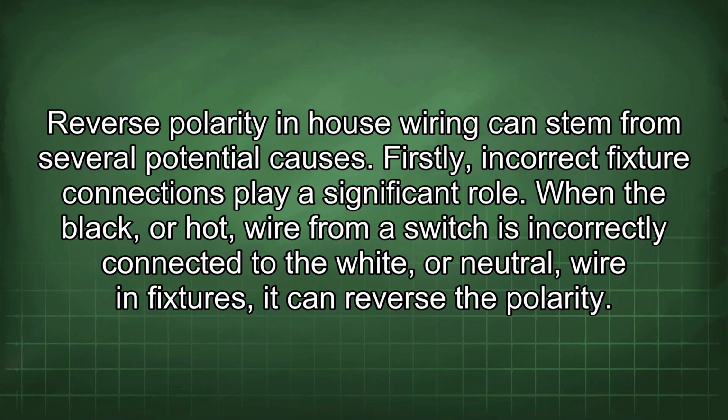Reverse polarity in house wiring can stem from several potential causes. Firstly, incorrect fixture connections play a significant role. When the black, or hot, wire from a switch is incorrectly connected to the white, or neutral, wire in fixtures, it can reverse the polarity.